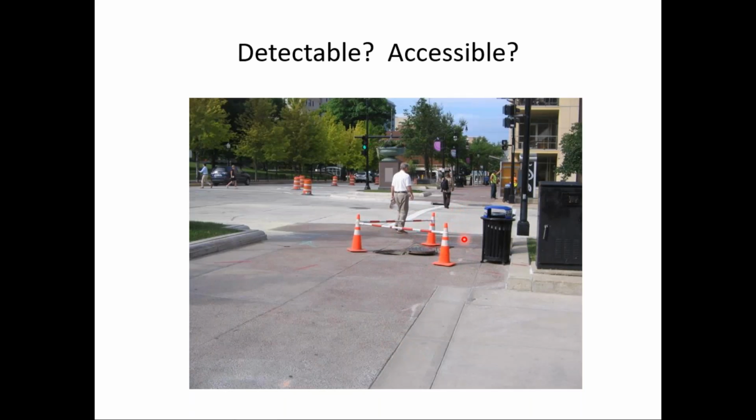But then I turned around and looked, and for a few minutes he disappeared. So obviously this is not really a good situation with an open manhole here and nobody sort of standing watch there. But in terms of traffic control, they did put some, this is a detectable barricade. Personally, I'd move it farther away from the opening to provide some distance separation there, but at least they do have a detectable barricade.